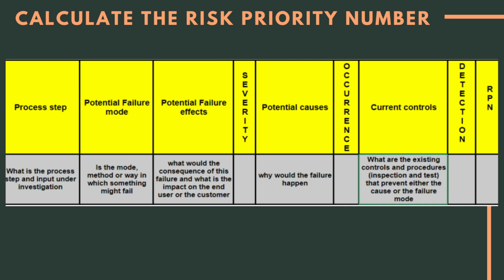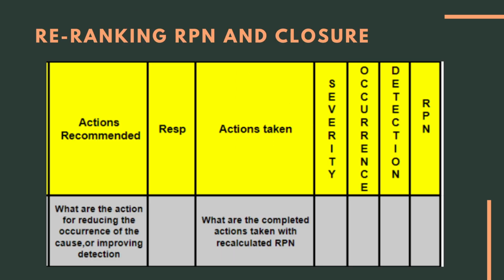Once the analysis has been completed and the risk priority number calculated, corrective or recommended actions are assigned to each failure mode. The severity, occurrence, and detection scores are then applied again to establish the new risk priority number once the actions have been applied. No FMEA should be done without a recommended action list to improve the system design.